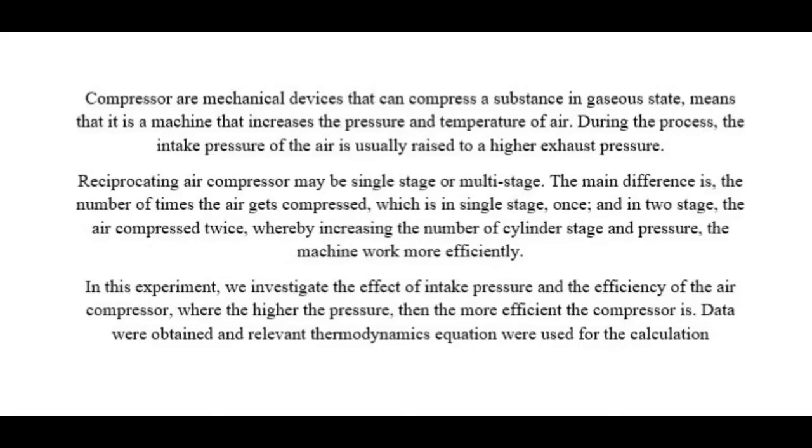the experiment. Compressors are mechanical devices that can compress substances in gaseous state, meaning that it is a machine that increases the pressure and temperature of air. During the process, the intake pressure of the air is usually raised to a higher exhaust pressure. Reciprocating air compressor may be single stage or multi-stage. The main difference is the number of times the air gets compressed, which is once in single stage, and in two stage the air is compressed twice, whereby by increasing the number of cylinder stages and pressure, the machine works more efficiently.